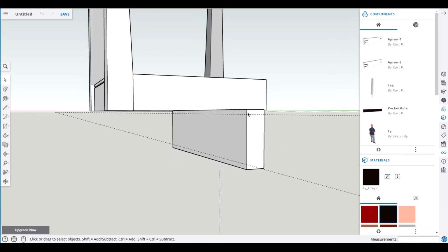So now we're going to create 2 1/8-inch squares again. R for rectangle tool. And we want it on the green, it looks like. So let's hit the left arrow key. And then we can see it here. So we're going to type in 1/8, comma, 1/8, enter. We have it. Now let's draw another one. Again, we're going to draw this up here. It's on the green. 1/8, comma, 1/8, comma, space bar.